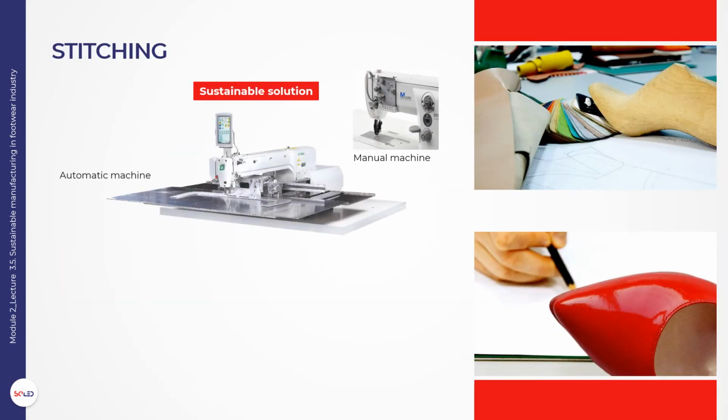Stitching. Automated stitching machines are probably the most sustainable solution for the stitching department. Large automata for functional stitching require special supports for each shoe size and for each type of seam. These systems are used for large production series. An experienced designer who knows how to use centerpieces for their shoe models can save a number of supports and therefore increase both efficiency and sustainability of the process.